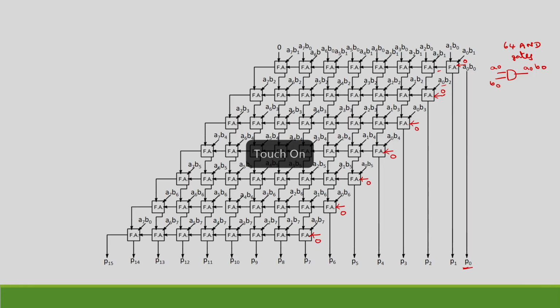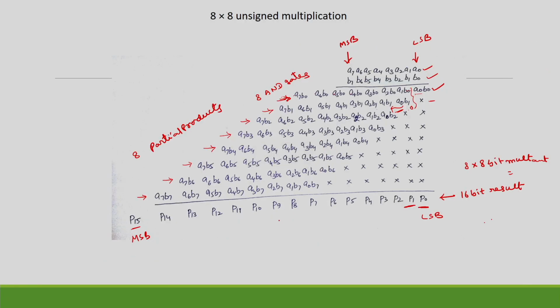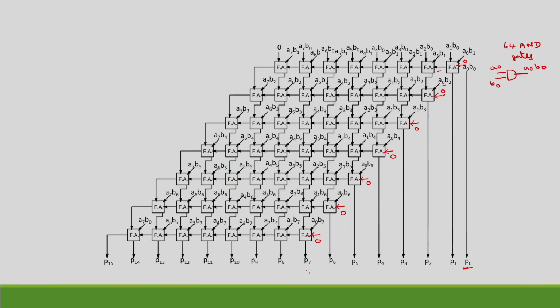Like that we can easily verify. So, this table can be mapped onto this architecture. There is a one-to-one mapping. Now, we will first write the Verilog code for the Braun multiplier, and then we will just repeat the codes of the ripple carry adder which we have discussed in the earlier lectures, and then the D flip flop. Then finally, we will instantiate all these 3 blocks to implement the final 3-tap FIR filter.